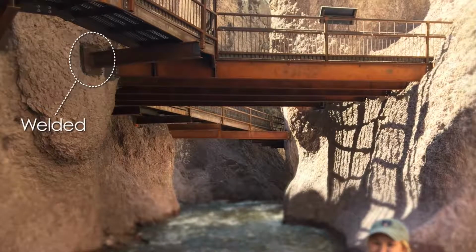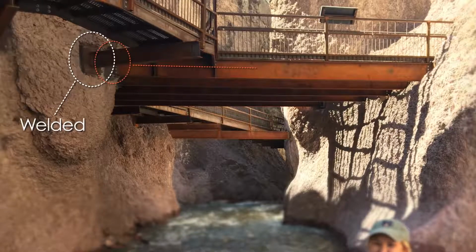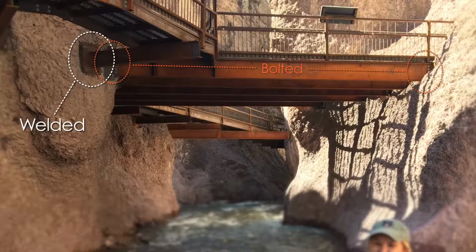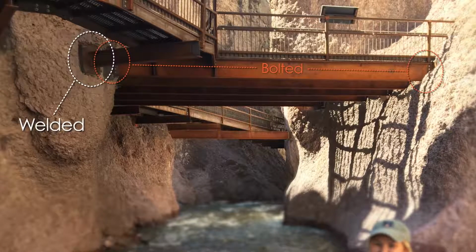But look at the beams that stretch across both sides of the canyon. At first glance, it seems like they're constrained on both sides, and we know that's bad engineering. But if you look closely, you can see that they're bolted to the anchor plate using slotted holes to allow the beams to expand and contract.